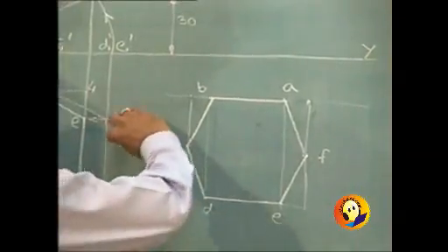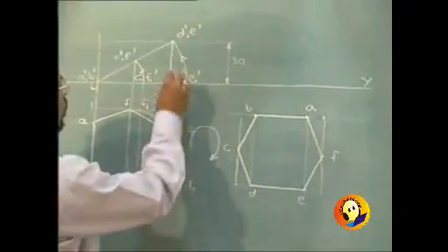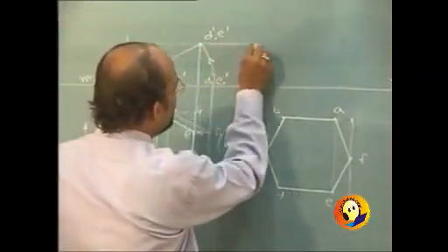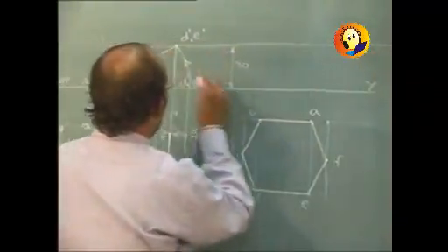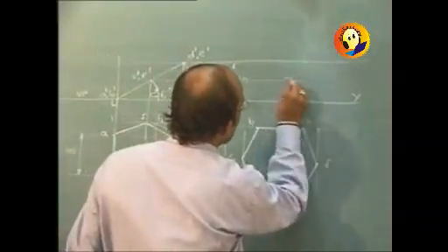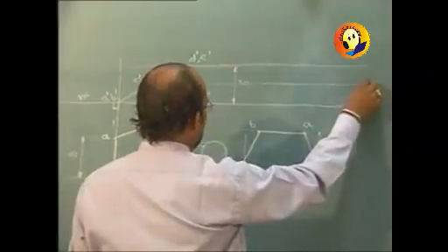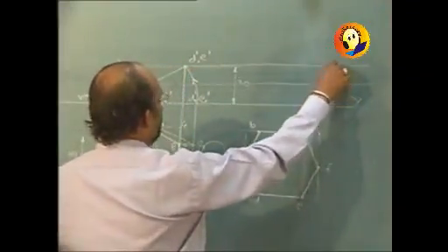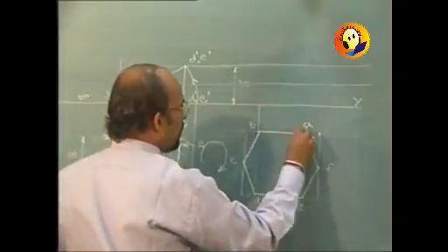This is again considered as the rotation of the plan, and rotation in one view is movement parallel to XY in the other. That was our first important rule, and so all the points will start moving parallel to XY, and these will be respectively the paths for points C and F and the path for points D and E. Draw projectors through each of these points.